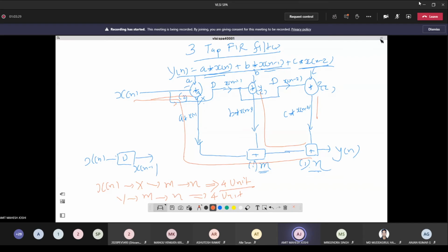In this example there is no loop. So if there is no loop for your retiming concept, then that allows me to insert a buffer without worrying about removing it. Because if there is a loop, then I need to always ensure that if I am inserting at some place, then I need to remove it. Why was I removing at the time of inserting? Because the number of delay elements should remain the same. But as there is no loop over here, I do not have to worry about removing it. I need to just think about inserting it.